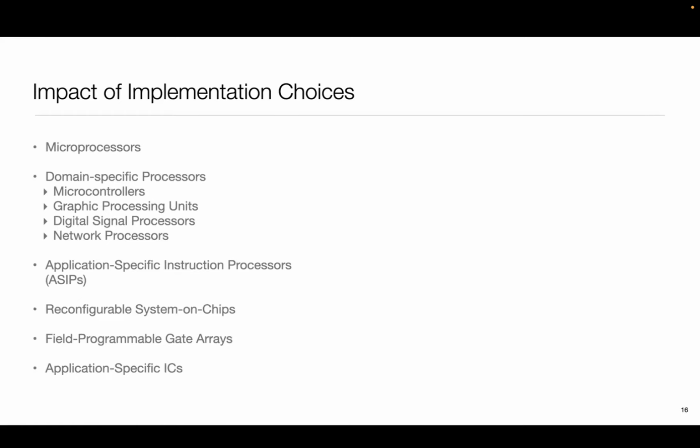We take this language and map it into the instructions or the primitives of my platform, whether it's the instructions of a processor or gates of an FPGA. In particular, in the case of FPGAs, since there's a lot more heterogeneity, like FPGAs come in different varieties, that compiler chain, which takes you from your algorithm written in some high-level language to this, is in itself a challenging task. So there's a lot of work happening there.